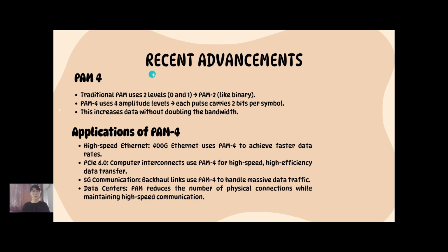Now let's move to the recent advancement of PAM. PAM4 is one of the recent advancements. Traditional PAM uses two levels, 0 and 1, like binary. PAM4 uses four amplitude levels, so each pulse carries 2 bits per symbol. This increases data without doubling the bandwidth.